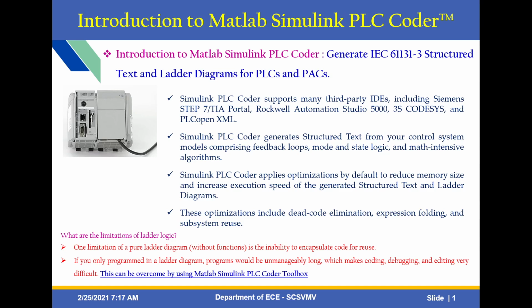Also, control programs can run distributed and independently rather than on larger controllers. No longer are thousands of lines of control programs required running in one controller for complex automation applications. Also, this increases the performance, improves reliability and simplifies the programs. This IEC 61131-3 is the international standard for programmable controller languages.